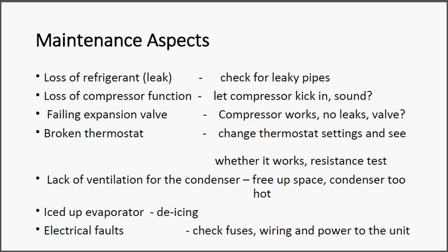Okay, maintenance aspects. Yeah, need to look at that one as well. So what happens when your refrigeration system goes wrong? And we're at the end of the presentation as well, you'll be pleased to hear. So a couple of things can happen. We can have a loss of refrigerant, so we can have a leak. If that refrigerant goes down, you check for leaky pipes.